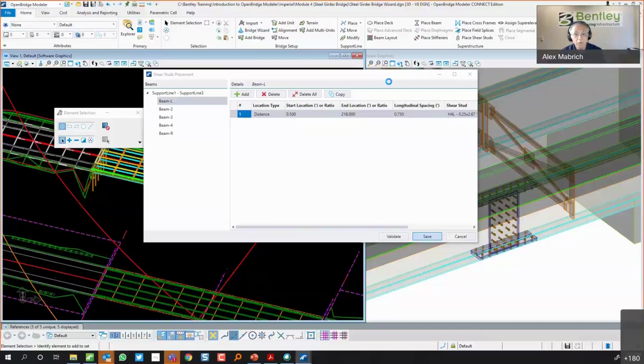The same. Remember, we follow the alignment. So if your alignment is on a curve, we just follow the alignment. And if you've got a curve, well, the beam will be curved. Also, we have the option to actually assign alignments to each beam. So for example, in steel, sometimes they want to use rounded radii, right? So yeah, you can also do it. You can also assign a specific alignment, a specific geometry, I would say, to specific beams, and the beams follow that.